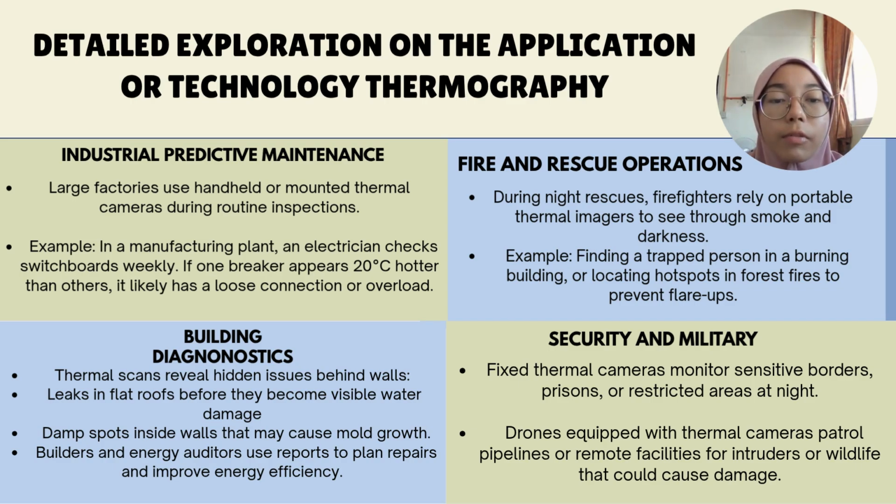The third one is building diagnostics. Thermography scans reveal hidden issues behind walls. It can detect leaks in flat roofs before they become visible water damage. Thermography can also spot damp spots inside walls that may cause mold growth. And builders and energy auditors can use thermography reports to plan repairs and improve energy efficiency.